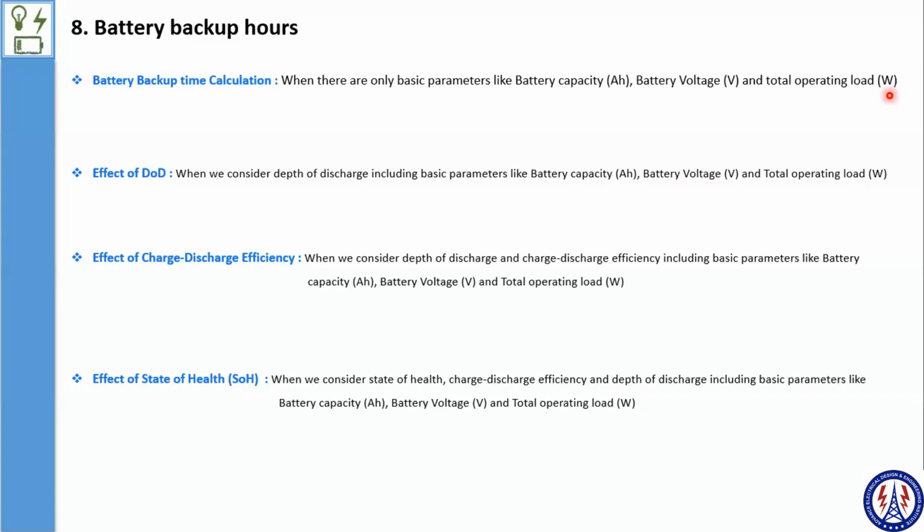So in the DC, because battery is in the DC application, on the DC side your VAH is nothing but kWh, VA is nothing but W. We can consider that because there is no power factor. So if I look at it unit-wise, Wh divided by W, the W and W get cancelled, and the remaining H is nothing but time, right?